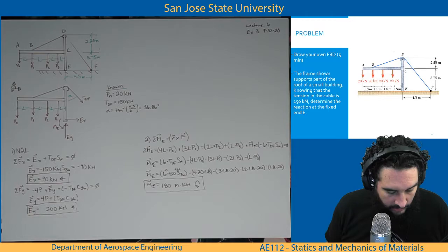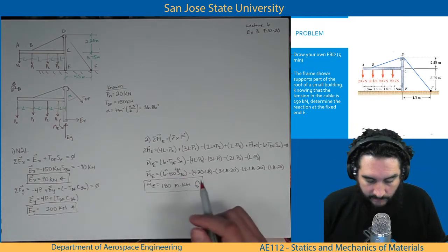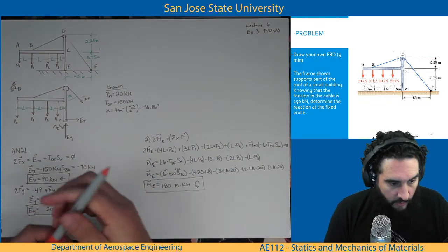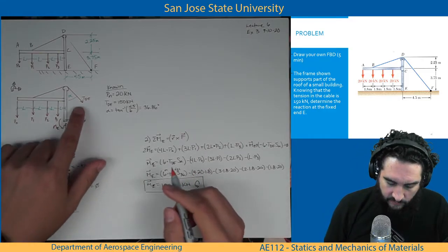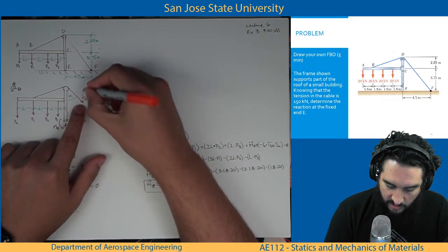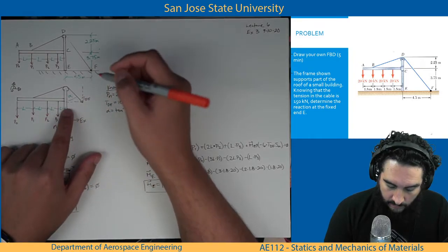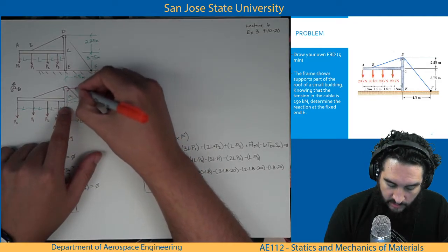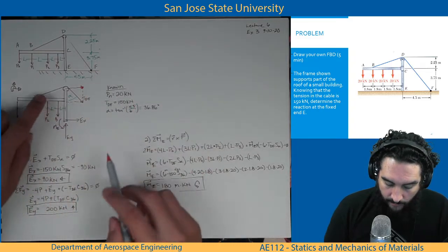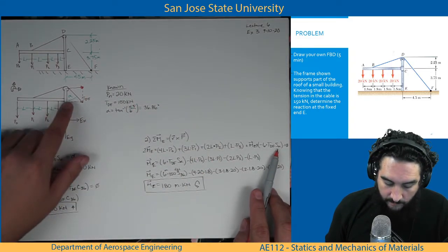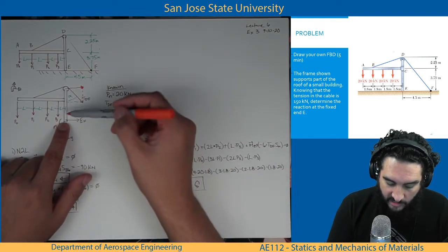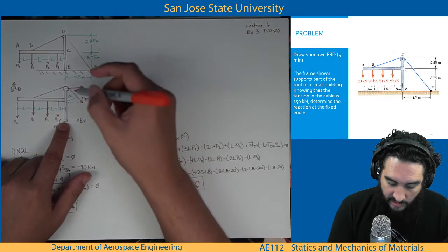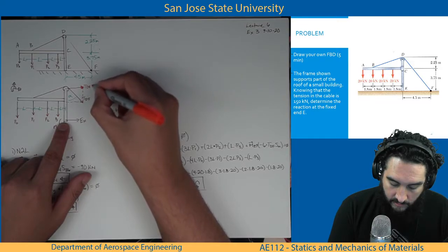So let's do this. Let me do this in orange. Okay, so the question was, why component of tension first? So let's talk about tension and how I'm going to break it up into components. If I break this up into sine and cosine, the sine will give us this direction, which did participate, sine of alpha, in the moment calculation about point E, because there is a perpendicular distance of 6 meters to the point of application of TDF sine of alpha.